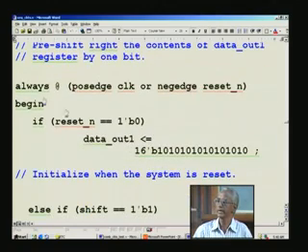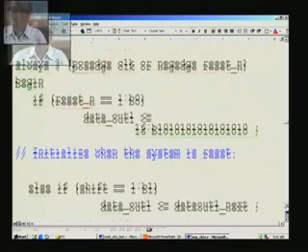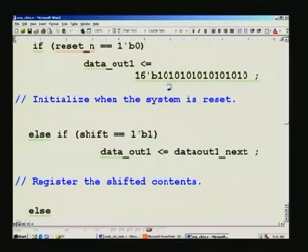register it when the event happens. The event is the positive edge of the clock, and here also, based upon the reset, we initialize, or rather preset, the desired value for the shift register, and in hexadecimal you can regard it as all AAs. It is a normal convention for designers to use AA and 55 for bit tests as such.